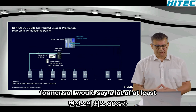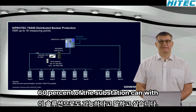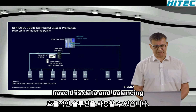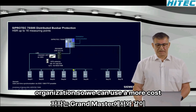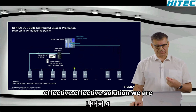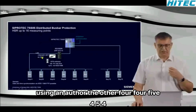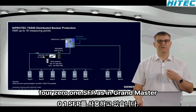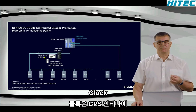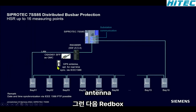So I would say at least 60% of the substations can live also with this solution, and you want to have this date and time synchronization. So we can use a more cost-effective solution. We are using an OSA, the OSA 5401 SFP as a grandmaster clock. And this OSA SFP can also directly connect to a GPS antenna.